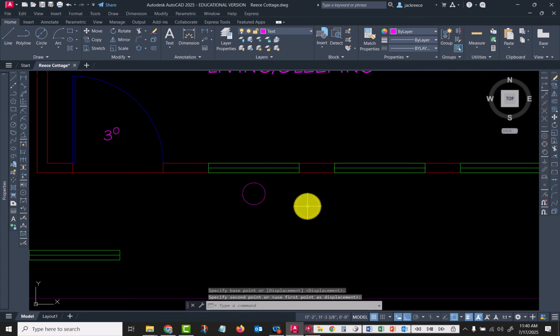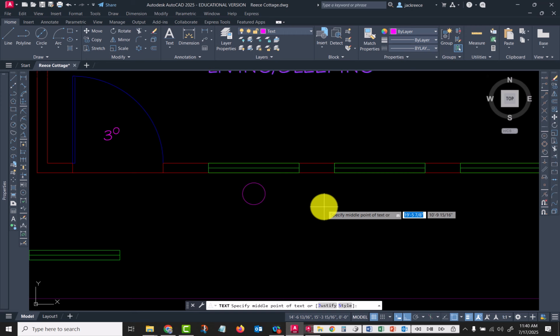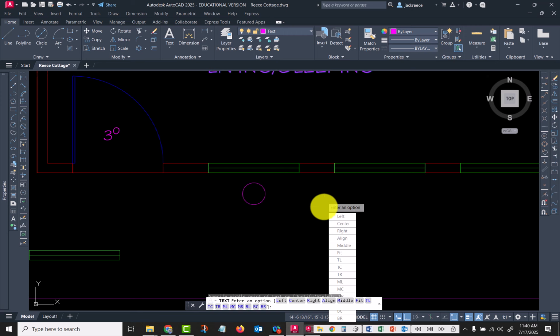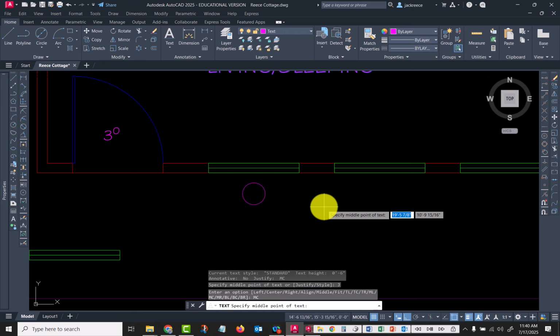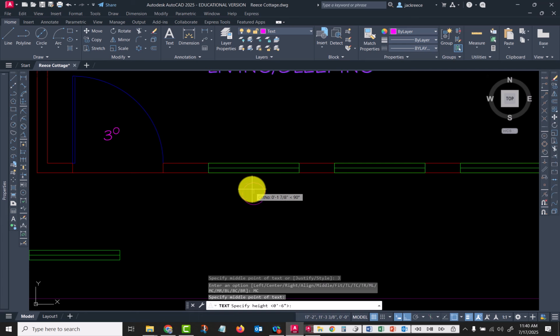In our architectural drawing classes, we would draw a construction line across there so that we get all of them lined up correctly, the appropriate distance off of the window. And so I've got it in there now. So let's do a single line text. And once again, justify. It should still be set to MC if you did this previously. If not, we'll change it to MC. And select the center of that circle. And this is going to be window mark.